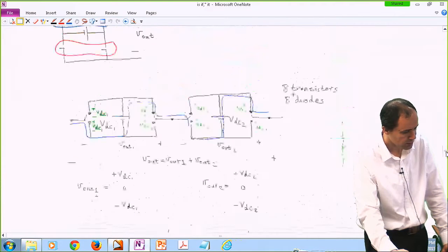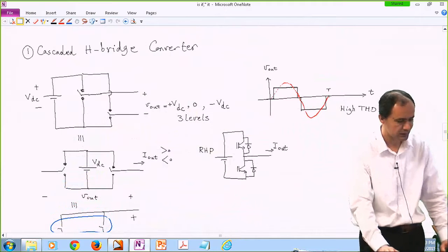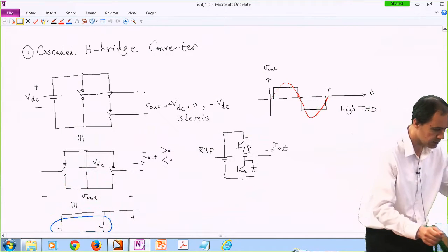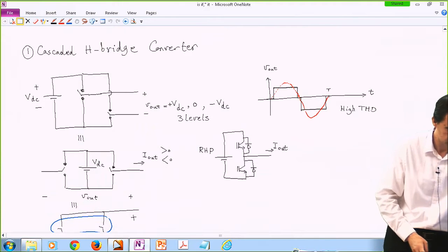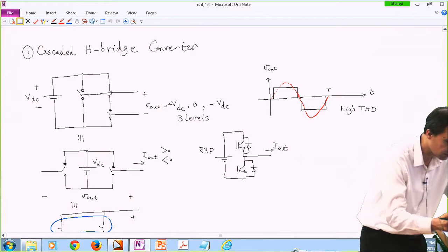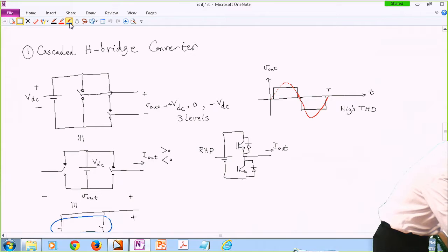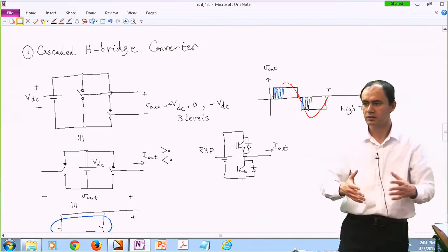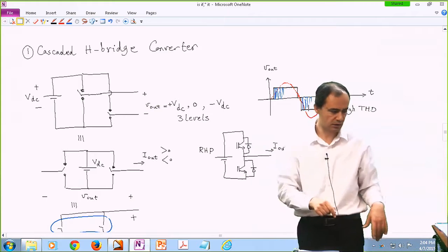Now, in the diagrams that I have here, I am showing a staircase switching scheme. But remember, this does not necessarily have to be a staircase; it could be PWM. You can actually switch between these 2 levels as much as you want, and also here. But since drawing those is a little difficult, I'm just using the staircase.